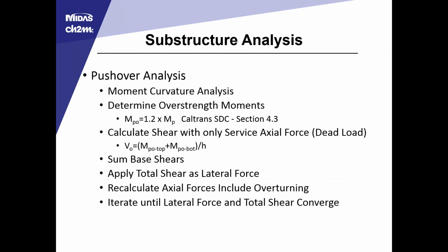Once we have that curvature, the basis of the pushover analysis is to take that ultimate plastic moment, determine the overstrength moments by multiplying it by a factor of 1.2 based on the seismic design criteria, and then calculate the shear relying on the dead load only, which is the service axial force. And we know the height of the column. We have the overstrength moment at the top of the column, the overstrength moment at the bottom of the column, and divide those by the total height and get the overstrength shear.